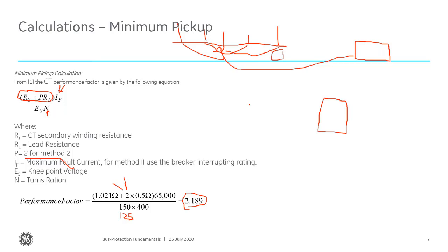There are some mechanisms that you need to account for. Also, when you do this, if you use multi-ratio CTs and you don't use the full tap, a large voltage can appear across that unused portion of the CT. There's even some mechanisms where you can use unequal CT ratios. Like I said, I don't recommend that. That's not a good idea. Thank you for your question, John.